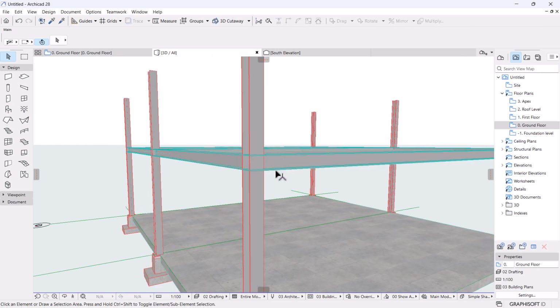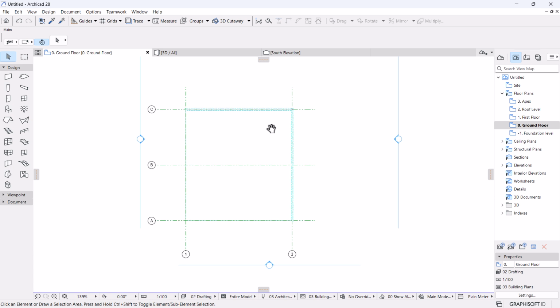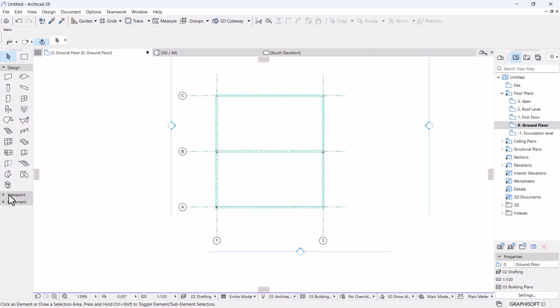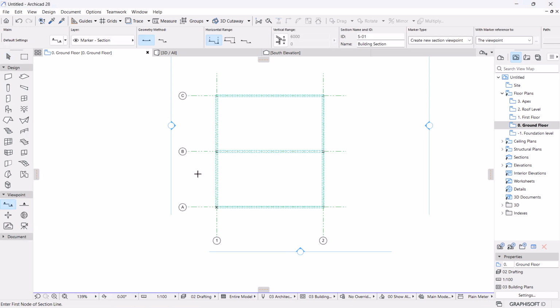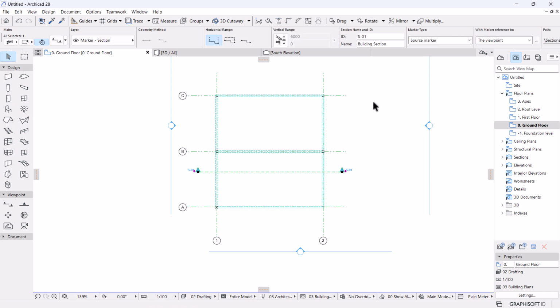Then we need to select all these beams. We can also use a section for accurate positioning. Let's go to the ground floor and place our section. Go to the viewpoint, then activate the Section tool. I'm going to draw a section from here across like that, with the viewing direction on this side. I want it to capture this framework. Right, so I can select the section, right click, or I can just come here under sections. It's been listed there, and then open it from there.